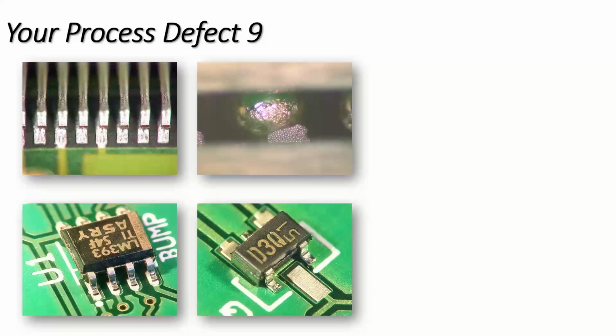But also look at the other things I listed: outgassing from the plating on the parts, since some parts outgas, and outgassing from the surface of the plating on the PCB, from vias, and from around solder masks. These are all things I've investigated and demonstrated by showing videos that they potentially can be root causes.